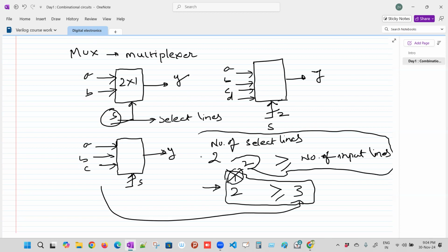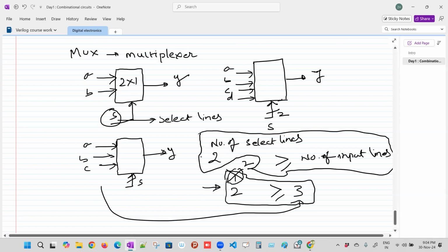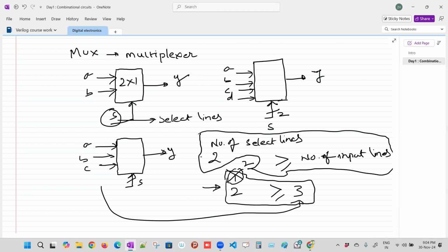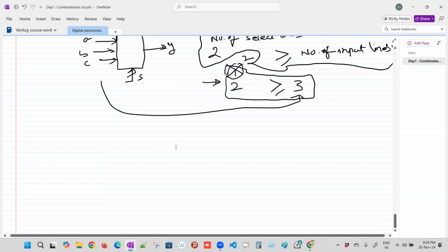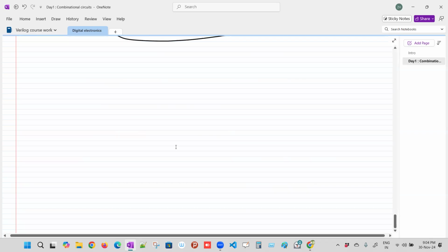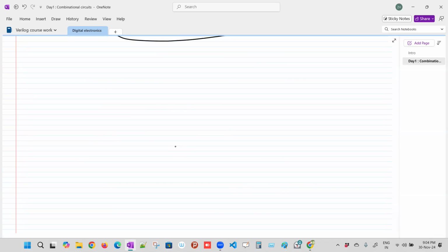In a Mux, is it necessary to always have enable? We do not have enable here, this is the select line. Enable is not required. Usually in making a 4:1 mux using 2:1 mux, we sometimes use enable, right? No, we don't use. I will talk about that.